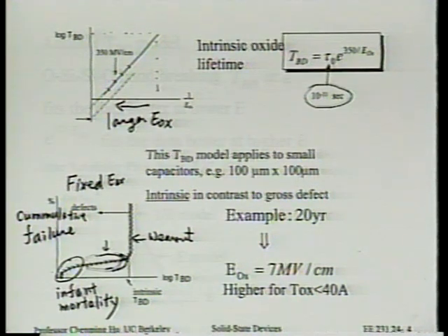You say, hey, why don't we just look at the overlap region between the N plus poly and the N plus drain or N plus source? Their situation is considerably simpler, right? The gate material and the source material both are N plus silicon. So the work function difference is 0, right? So the voltage you applied is basically all across the gate oxide. Is that right? So from that you can see we're pushing close to, it's using about 9 megavolt per centimeter.